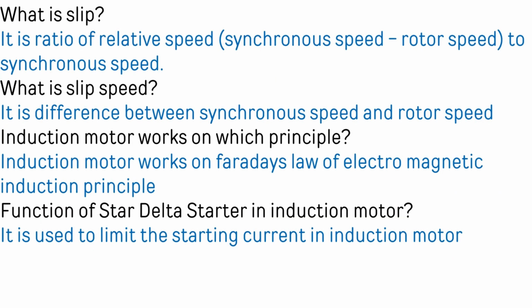What is slip? It is the ratio of relative speed to synchronous speed, whereas relative speed is nothing but the difference between synchronous speed and rotor speed. What is slip speed? It is the difference between synchronous speed and rotor speed. Induction motor works on the principle of Faraday's laws of electromagnetic induction. What is the function of star delta starter in induction motor? The star delta starter is used to limit the starting current in induction motor.